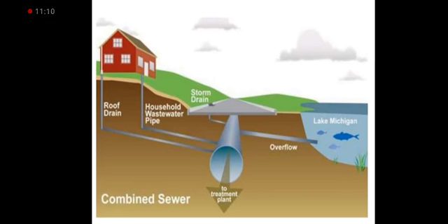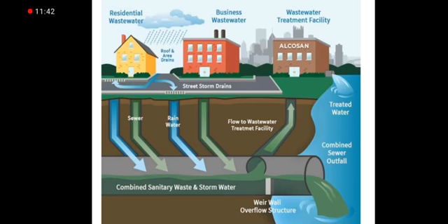When we are going for the separate sewerage system, there are various types of shapes for the sewage pipes, but mainly we use two shapes, that are circular and oval shape. When we are going for the separate pipeline, that time we use circular shapes. You would have seen while the construction is going on, the pipeline below the ground for the sewage will be of circular shape, or else oval. When we are providing the combined sewerage system, that time it used to be oval in shape.